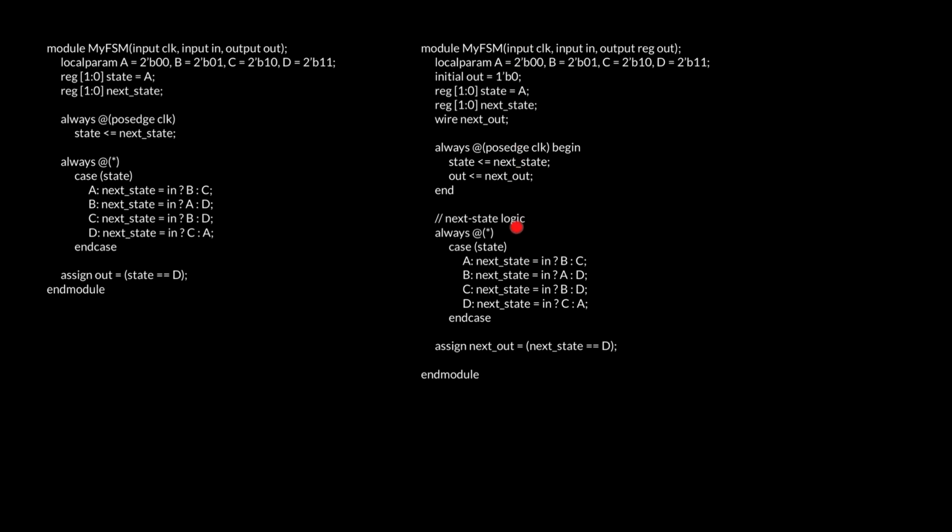At this point, we're basically done. It's important to emphasize that the state diagrams for these two finite state machines are identical. All we've actually done is change the state encoding. We haven't actually changed any of the state dynamics. So if you were to take this finite state machine and draw the state diagram, you would have 4 states and they would transition according to the rules here.